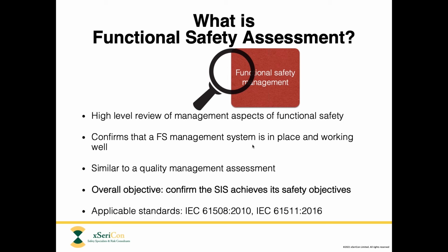Functional safety is covered by a series of international standards. The overall standard is IEC 61508, and that is applicable to all industries. And then for many specific industry sectors, there are standards derived from 61508. For example, for the process industry, the relevant standard is IEC 61511. And there are a whole set of other standards, for example, for machinery safety, for medical devices, for transport safety, for nuclear, and all of these others. But the functional safety assessment requirements are relatively similar between all of these.